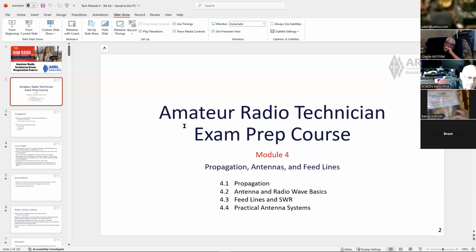And this one you can put up in several configurations. Horizontal, you can actually use it vertical, but horizontal, you can put it sloped, inverted V, L, or circle, so that you can put it in several different configurations. And what I normally do with my dipoles like this, I run them from north to south. I can still get into Canada and north and south, but it's primarily for east and west, as Howard said a while ago.